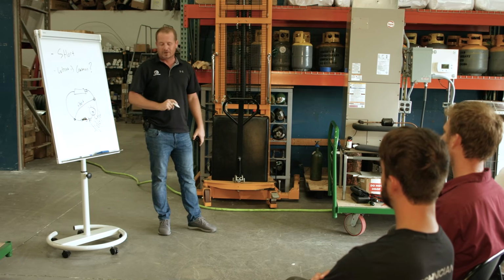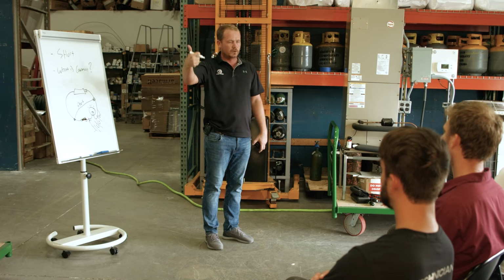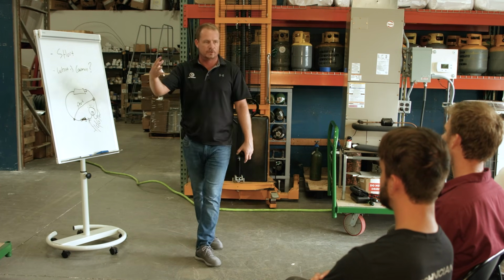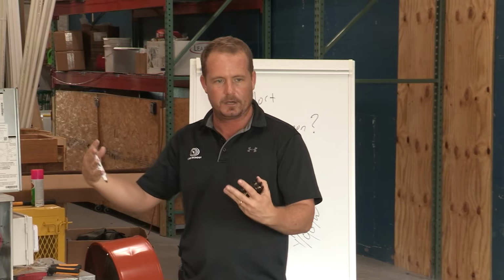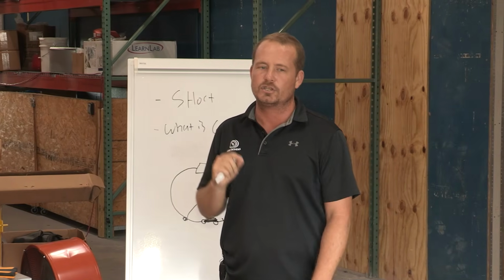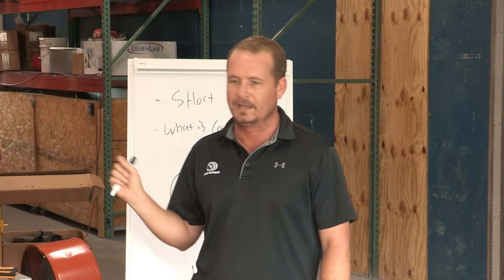But most of these circuits are in between our switch and our load. Our load is whatever they're turning on and off: your reversing valve, your contactor, your blower relay, your heat relay, your gas furnace, whatever it is, right? They're turning something on and off. But what happens if those two touch each other? That's what we would call a switch leg short. That's a term I completely made up, but it's the best one I can come up with.